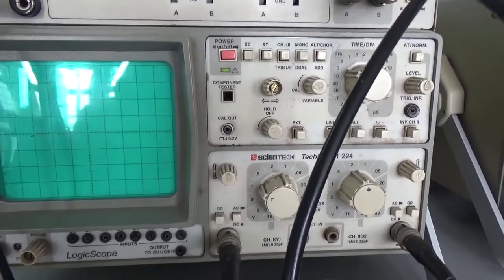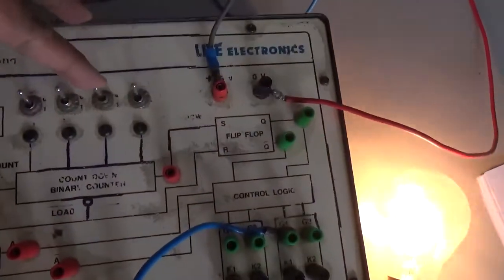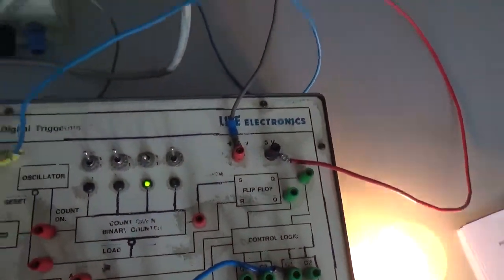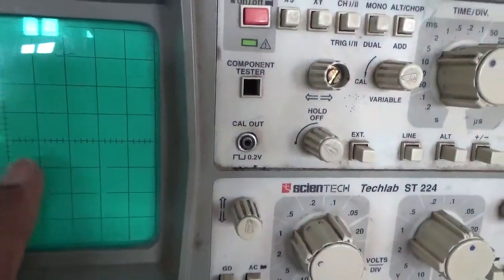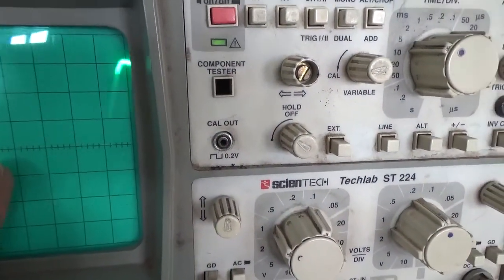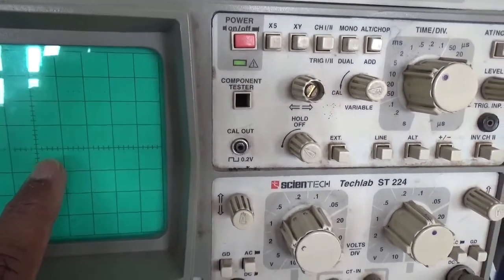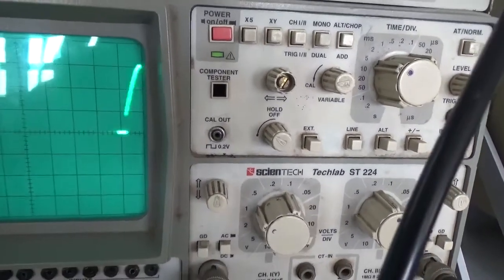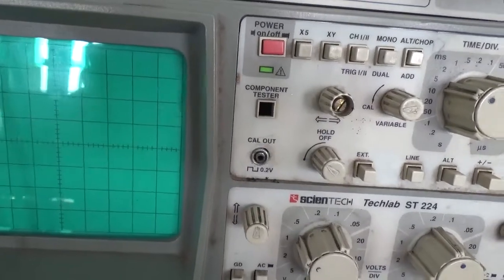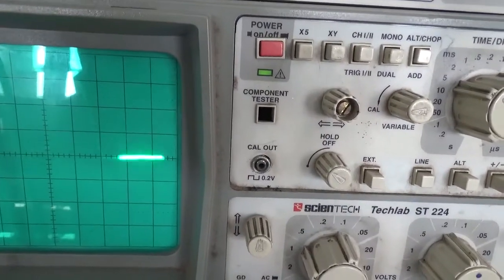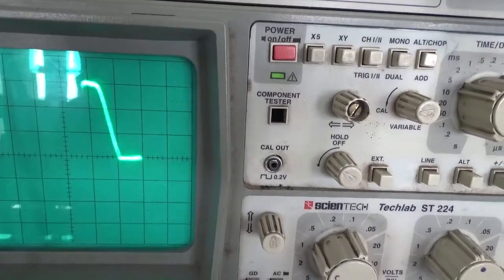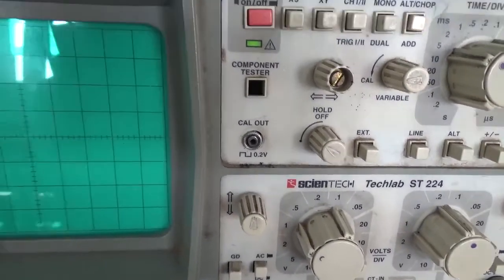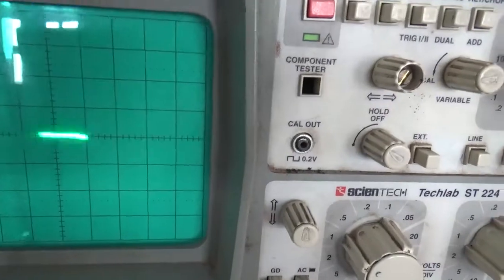And let me change the digital data here, binary data. Let me change it to 2. 0010 means 2. So you can see there is a chopping of the waveform that's happening at 36 degrees. 36 degrees is the firing angle. I keep on changing the digital data, and you can see the cutoff of the waveform. This is for digital data 6, and I'll go for 8 now. For 8 we can expect alpha 90 degrees.